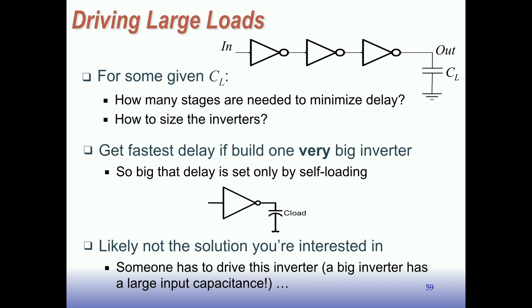It's a similar thing here. We kind of want to match the internal capacitance of the small inverter to the huge internal capacitance. So it makes sense we kind of flare up and gradually get bigger and bigger. Right? Intuitively, it's going to be more efficient to do it that way.